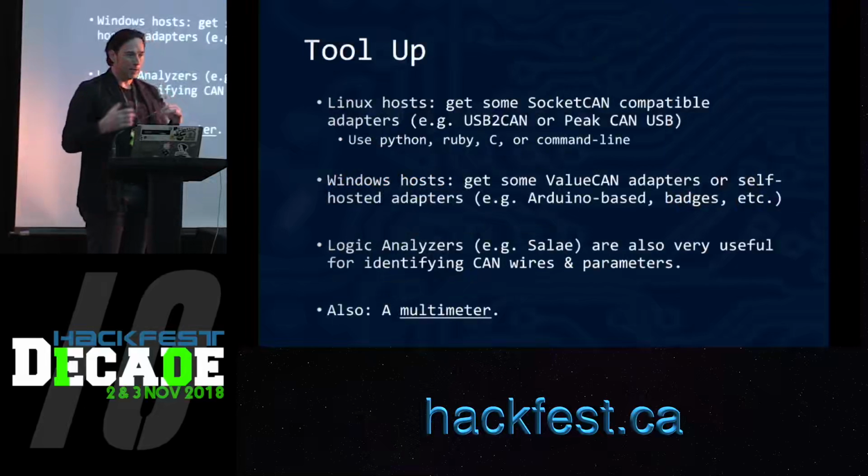Now, if you're the kind of person that really wants to live in Windows and likes to connect to Arduino consoles over serial, you could totally get Arduino shields that are CAN bus adapters, and have a little Arduino serial connection and do your CAN bus things. You can also do the Linux option where you actually have a CAN adapter in your Linux VM, and these are USB to CAN adapters.